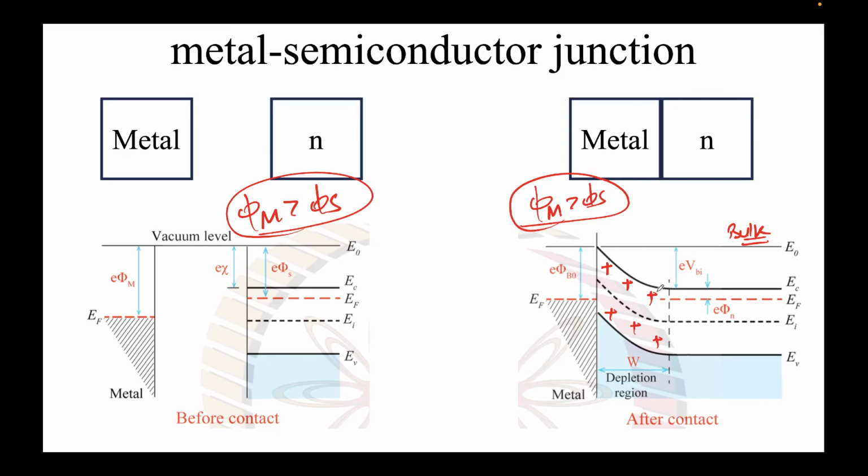So the electrons which are here, if they have to travel to the other side, they have to cross this barrier, right? And vice versa. If the electrons have crossed from here to here, let's say we are applying a forward bias, that is metal to the p side, then there will be holes which have to traverse, or on the opposite side, the electrons have to travel from this side to this side. There's still an energy barrier that it has to face. This barrier is also known as the Schottky barrier, essentially.